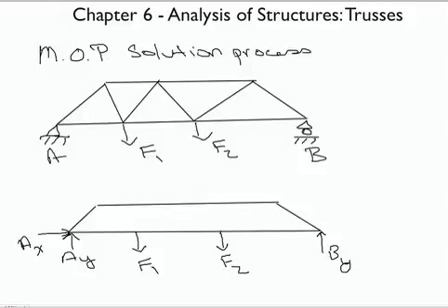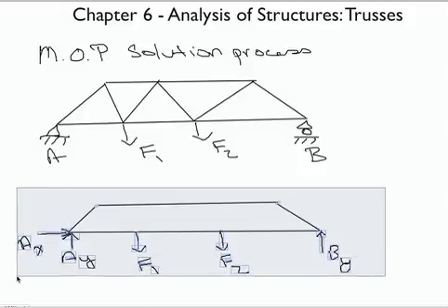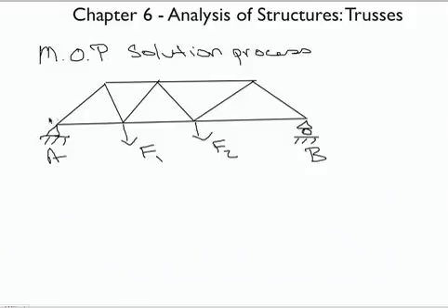So if we have all those reactions, we can then pick a point to attack. It doesn't matter which. Like I talked about before, you're propagating known information. You know information here and here because you solved for the reactions, and you just have to make sure you pick a place that has no more than 2 unknowns. So here you have both reactions and you don't know these two pieces, so we can just start at A.